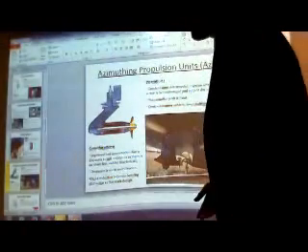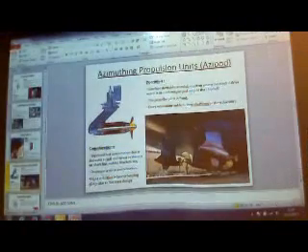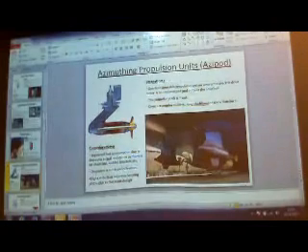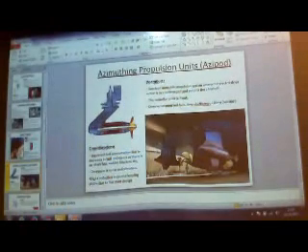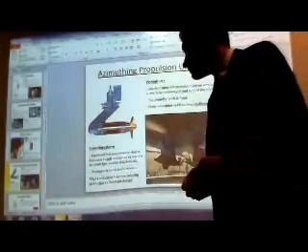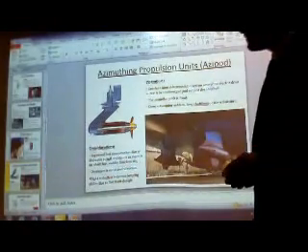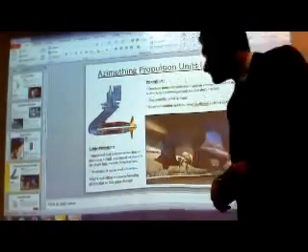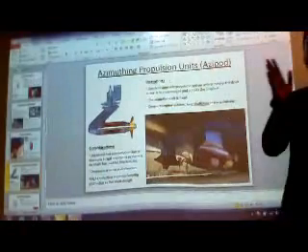It improves fuel consumption due to a decrease in hull resistance, because there is no shaft, there is no propeller shaft, so there are fewer things that are going to create drag at the faster speeds. It decreases noise and vibration. There is a slight reduction in course keeping ability due to the flat stern design. Yeah, you are not streamlining the flow.